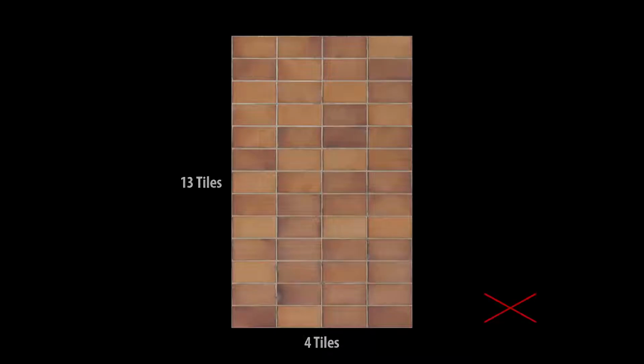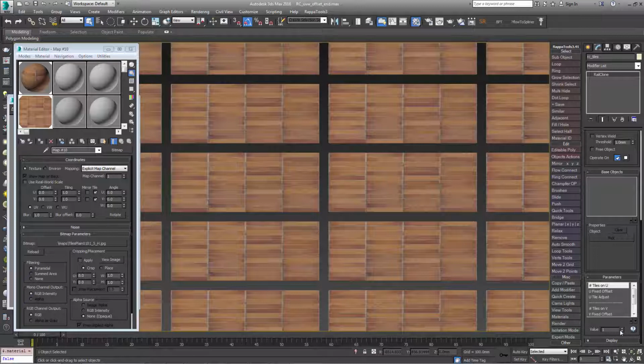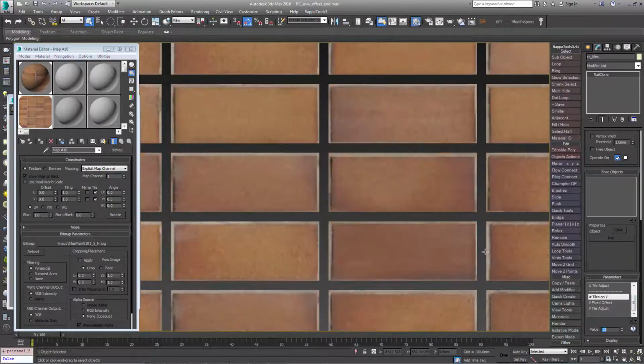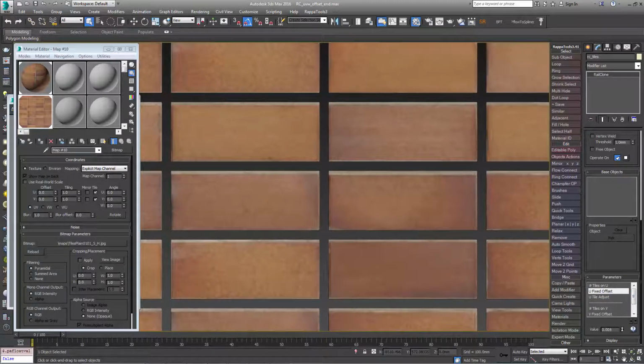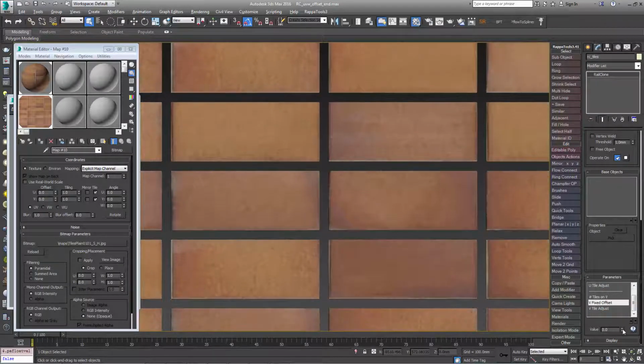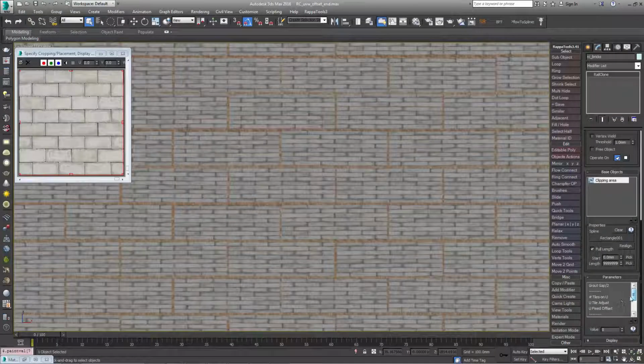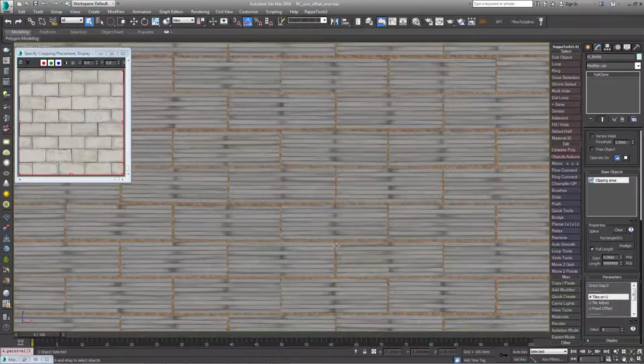In this tutorial, we use multiple UVWXForm operators to separate the controls for the U and V axis. In addition, we'll automatically adjust the segment's UVWs so that they scale to fit an individual brick to save you from having to manually adjust the UVW coordinates on the source geometry. And then building on this example, we'll finish up with a more advanced example that calculates the offset required to extract textures from a running bond pattern automatically. This is useful for bricks, which are often found on texture sites in this format.